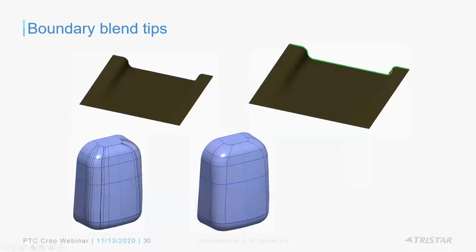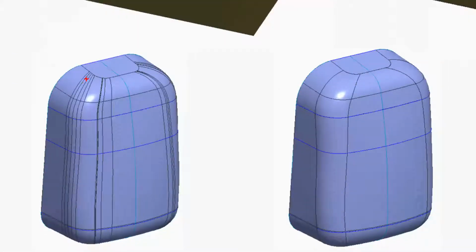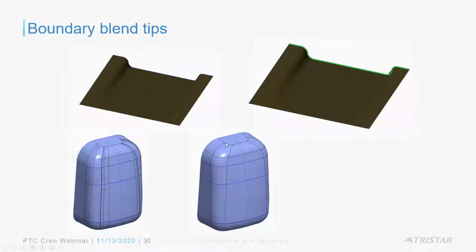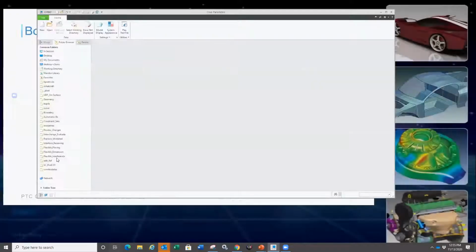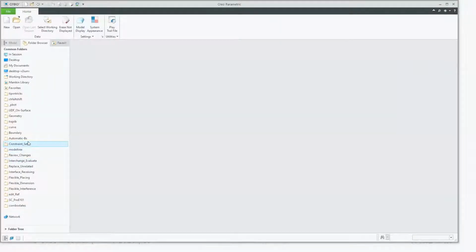Oh, one little thing here. You might have seen surfaces sometimes, when you do surface modeling, with control points having issues, wherein you'll have to tell the software to get rid of those geometries. It might have issues from a manufacturing standpoint, or when you thicken, or for downstream applications. The way you do it is you go to control points and fix it, but there's a nice little better way than that. Sometimes it works, sometimes it doesn't, but it's a very useful tool.